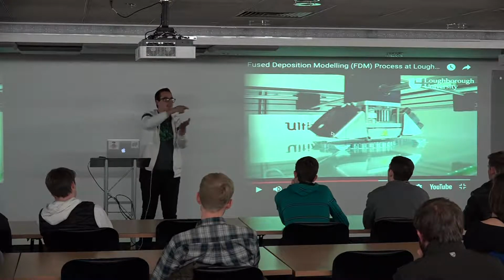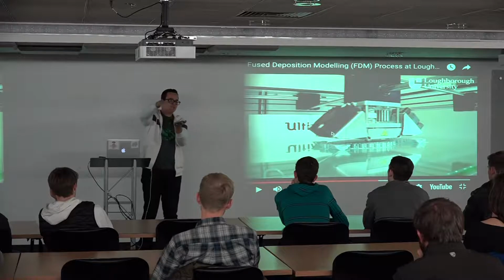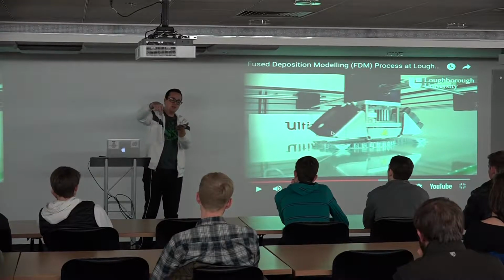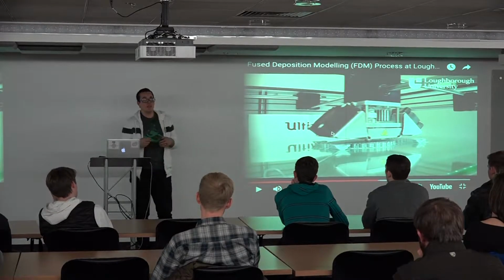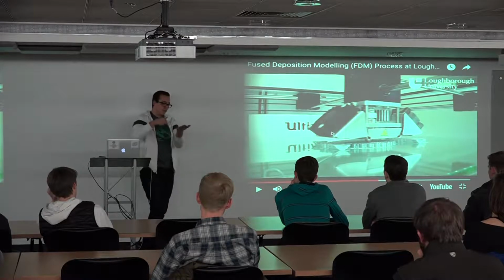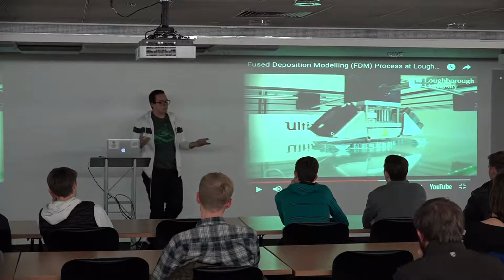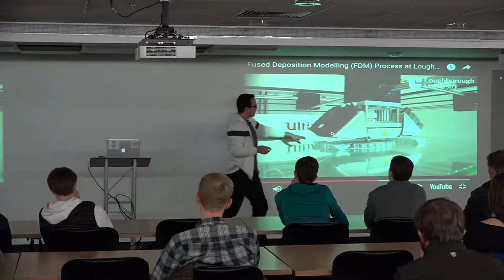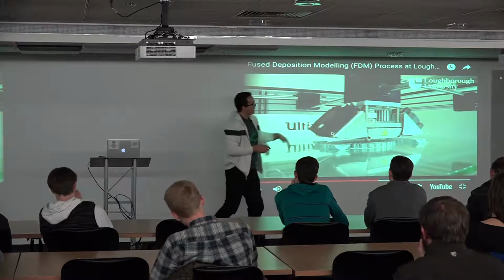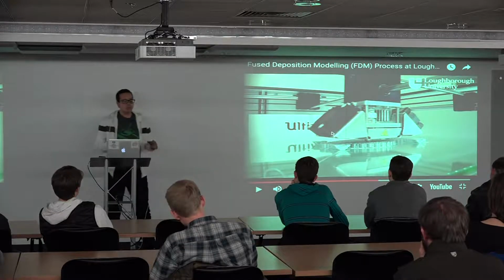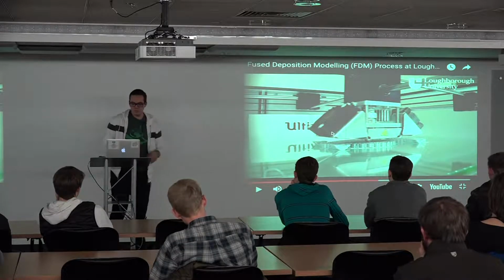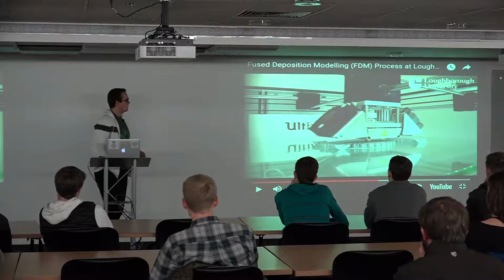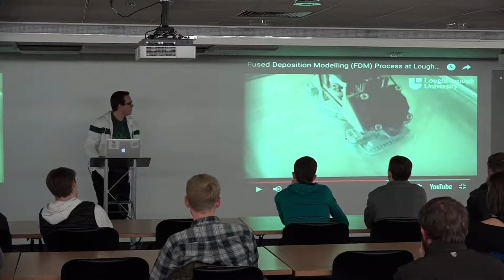You'll be doing that in midair. If you can imagine, you've got 2 towers, then nothing underneath them, you'll be spitting out plastic into midair. And some printers will actually be able to, they call it bridging, bridge that gap moderately well. But if it's something big like this, especially this is a whole base of a race car, you'll need to generate some support material underneath it. And I'll go ahead and lead you through how to do that.